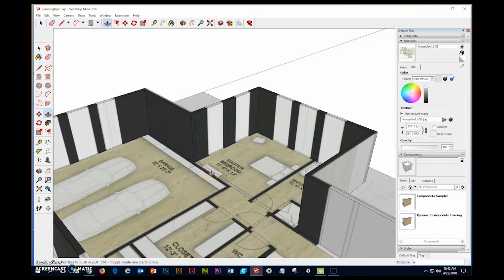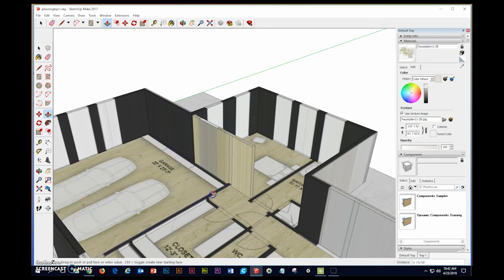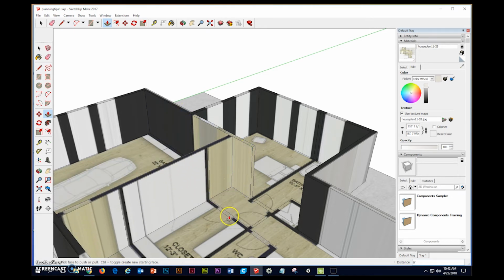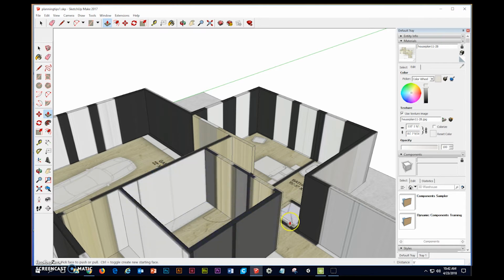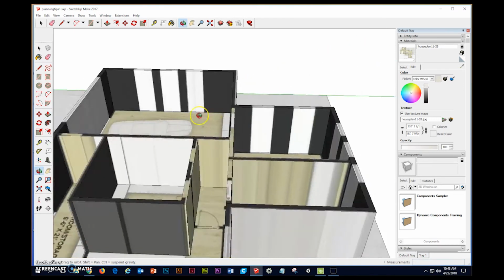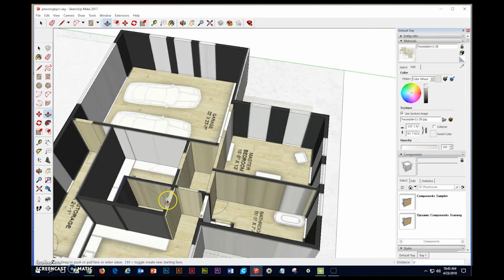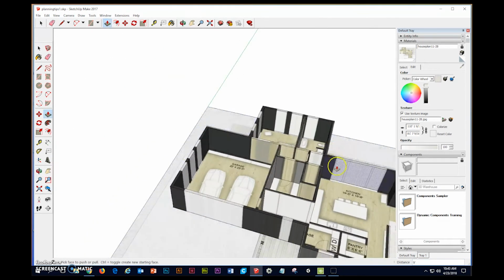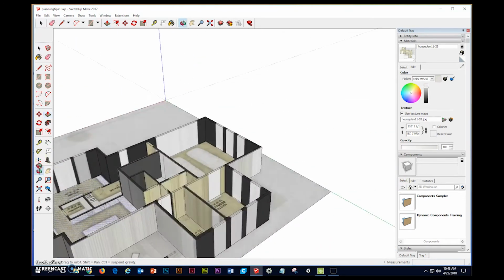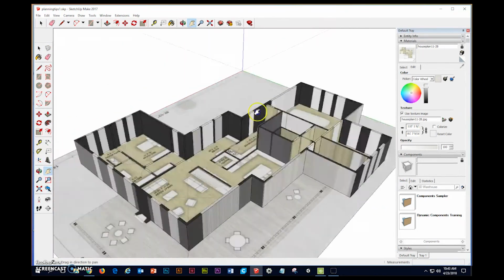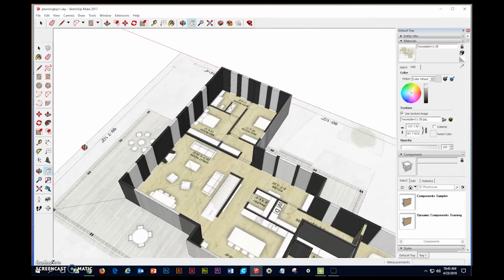After that, it's just a matter of finding walls, clicking, letting go, and clicking on the top edge of your exterior wall. And by moving these all separately, it takes a little bit more time, but if you find out you have something messed up at some point here, it's a lot easier to fix than if you have to cut it away from all the rest of the walls in order to fix it, which is what we had to do in the past. So this makes things a little bit easier. This little hand tool is your friend.